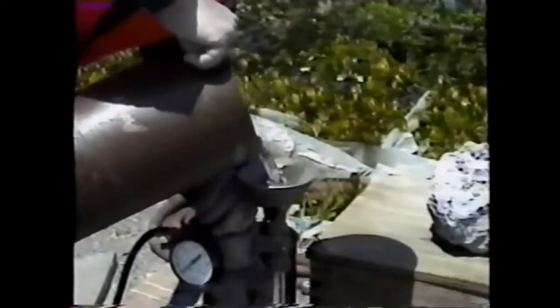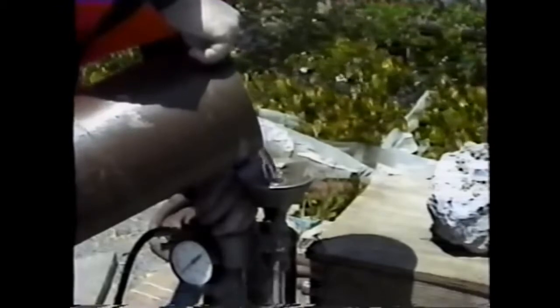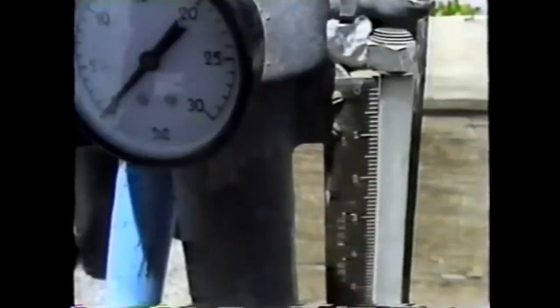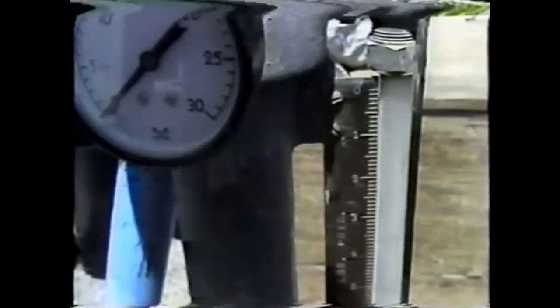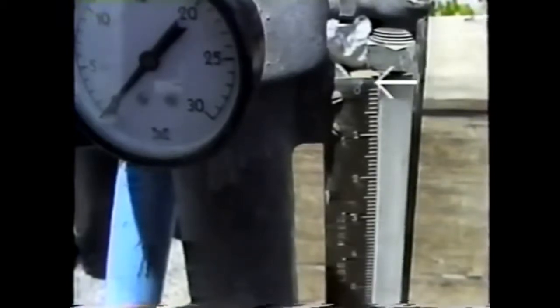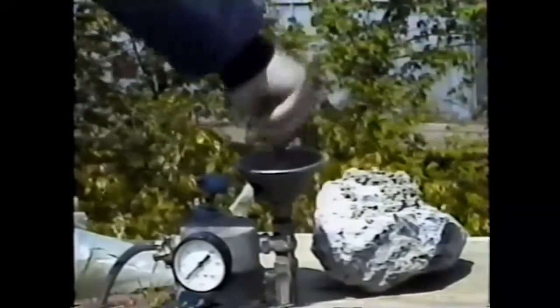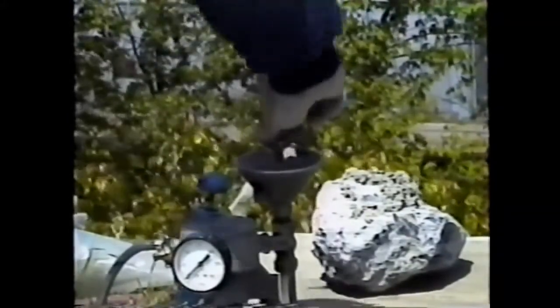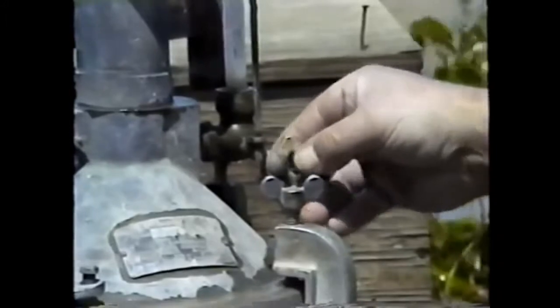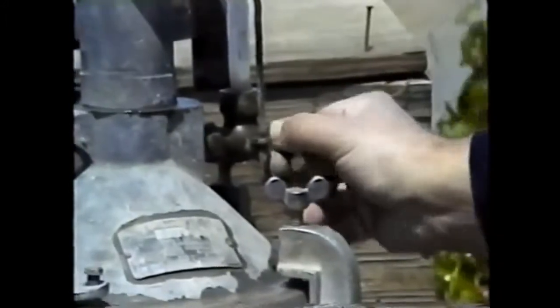Next, water should be poured through the funnel valve until it stands at a level slightly above the arrow mark on the graduated scale. The funnel valve is then closed, and the level is adjusted to the arrow mark by drawing off just enough water through the lower petcock.